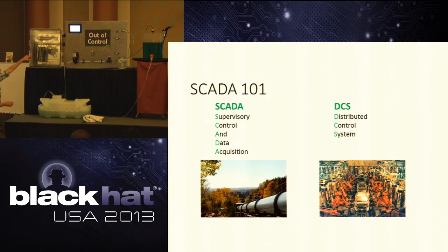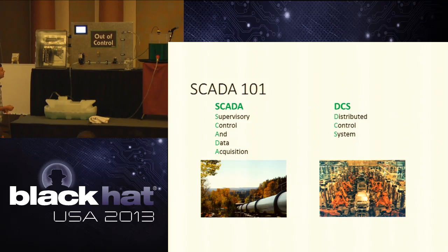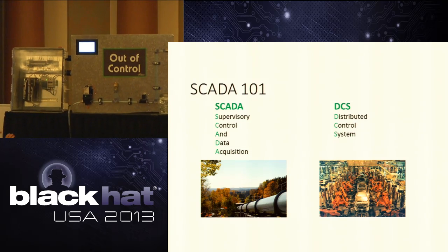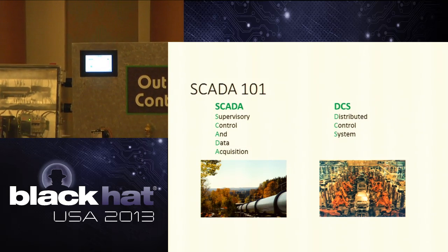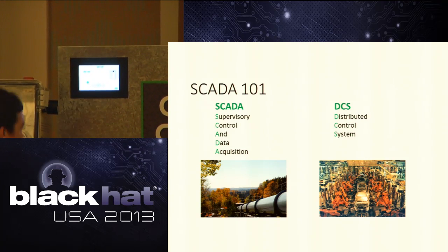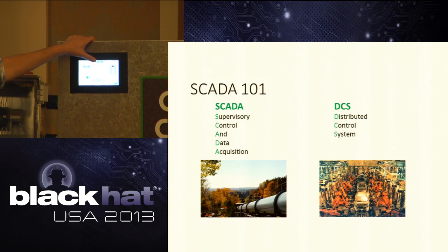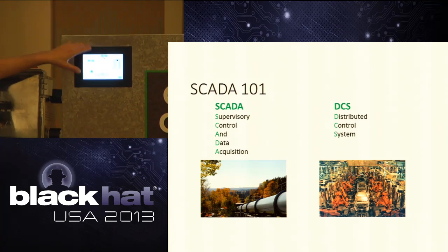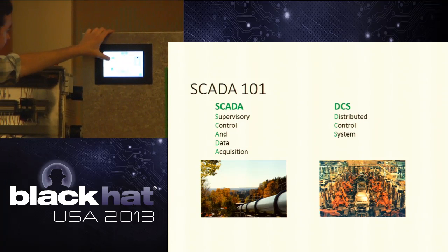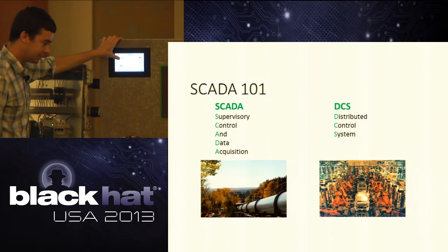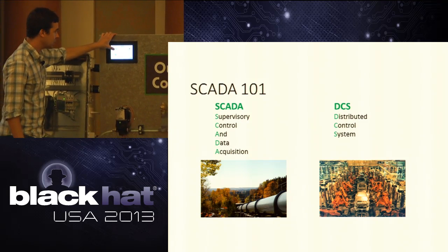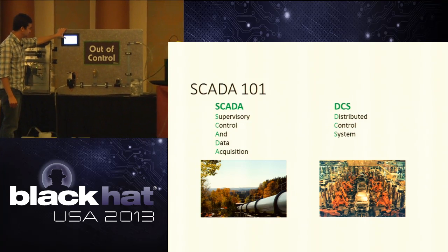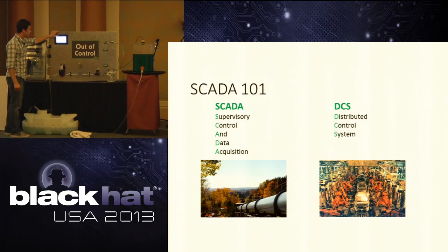One other thing that we have up top is this little screen right here. That screen is called an HMI, and that's the visualization of the process. We can give you a quick show of what it looks like to actually work. All this stuff is touchscreen, and you usually see these installed in the field. The HMI is the operator's view into the process, and it also allows some control. And you typically see alarms pop up if you have any conditions that are met on the HMI.